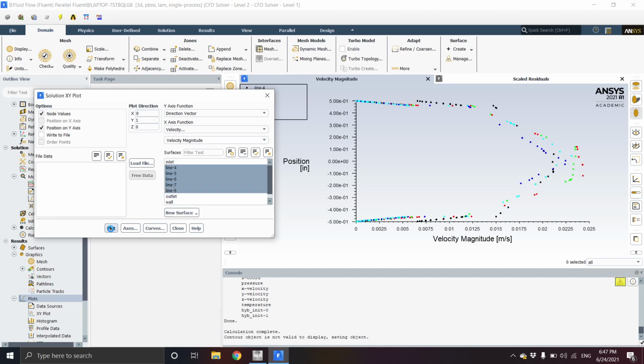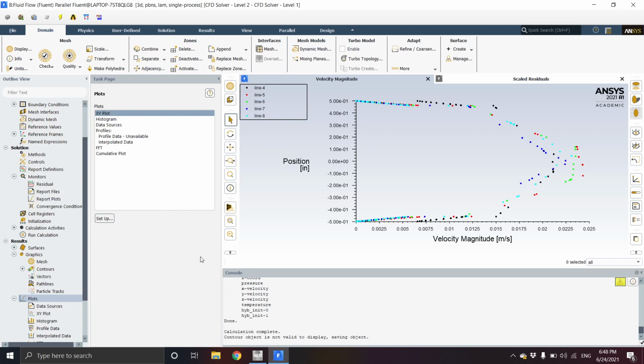So compared to our 2D problem, we can see that our velocity is developing a little bit sooner, and it's not becoming more quadratic as we go. There can definitely also be some errors. So most of the time, in this type of problems, as we can see, the 2D analysis gave us a very accurate representation of the problem. So sometimes we want to take the 2D instead of the 3D just to save time and computer space. So that's definitely something to consider. So in future tutorials, we will work on different case studies.